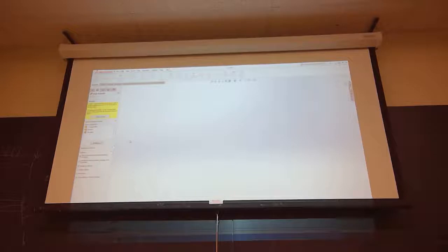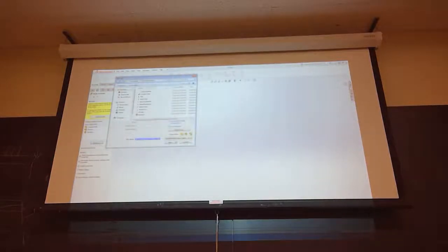Obviously to build an assembly, you need the parts. That's why the first thing you see here is a list of possible parts. Usually that list isn't very good, the one it comes up with automatically. It just pulls from its cache. But you can click Browse. Just follow what I do. I'll go slowly. Click Browse, and then navigate to the training rocket zip file.